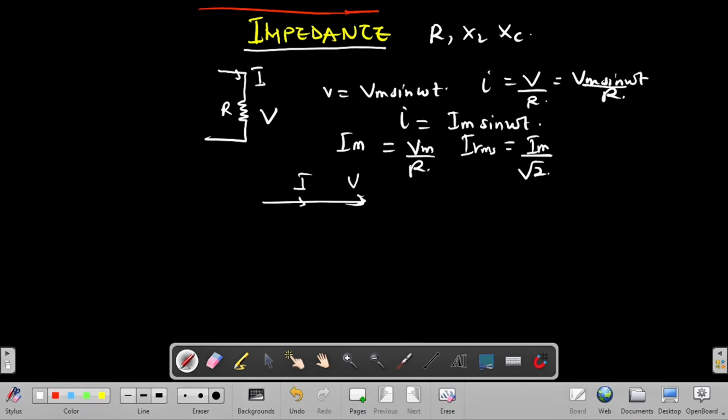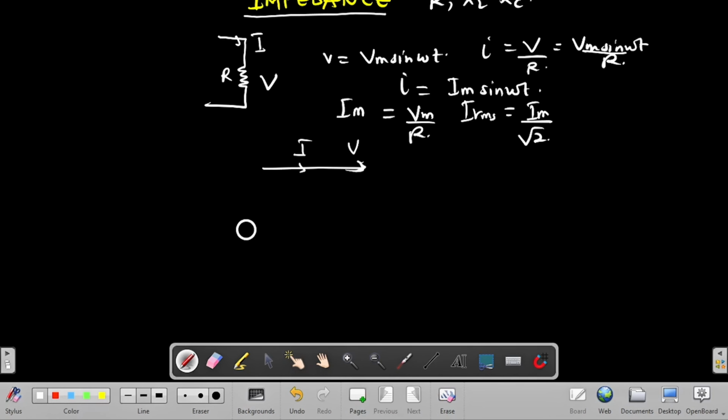Now let's move to a circuit which has an inductor. So this one was just a current through a resistor. Let's go to a current in an inductor and see the relationship between the current and the voltage. An inductor is a circuit element which we didn't talk about in the DC because it's applicable in the AC. It works by creating a magnetic field in its core. An inductor is something like this, just a coil around any solid material. Once current passes through, a magnetic field is created within this coil, and it is purposely used for magnetization, whether in memories or in transformers or whatever.